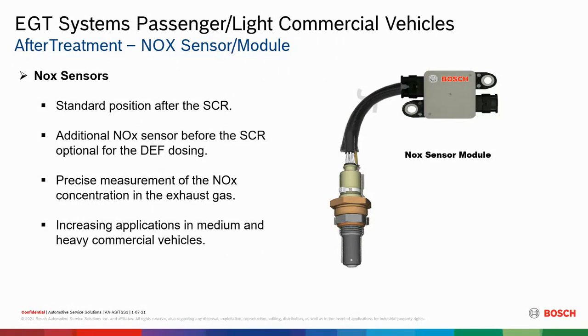And just a little tidbit here, just so you know, we call them NOx sensors, but honestly, they're an oxygen sensor. They are doing the same process that an oxygen sensor or a wideband sensor does. And it's really not measuring the NOx, it's measuring the oxygen content in millivolts.